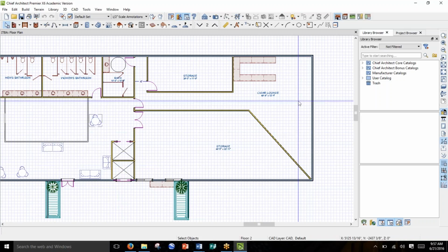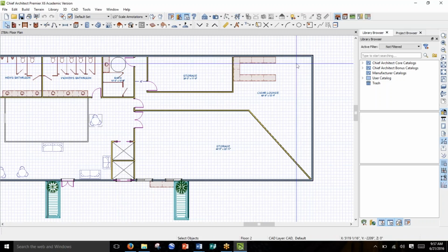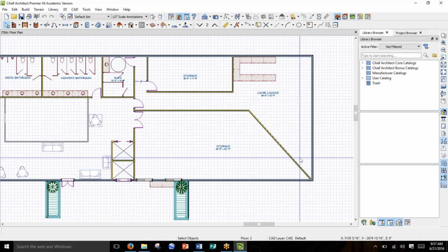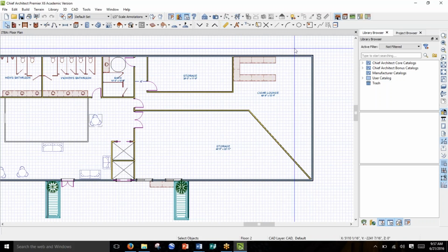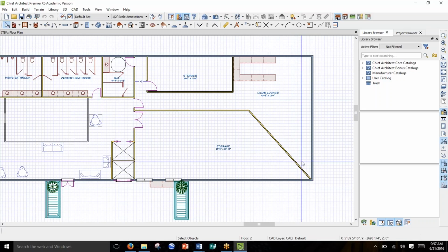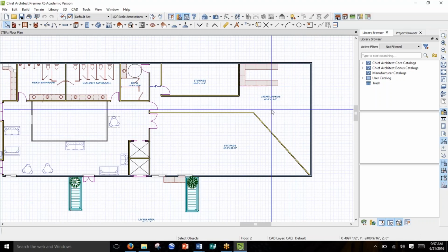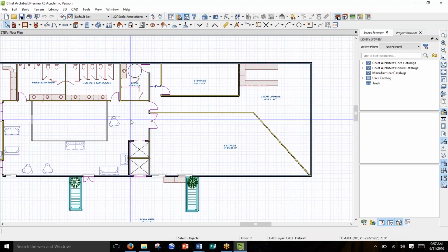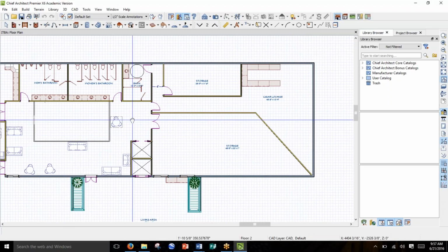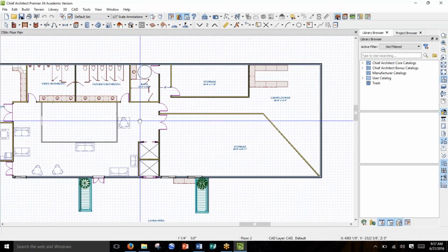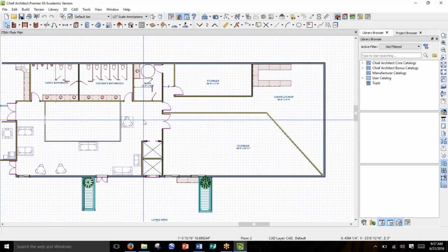If you could show me a diagram of some measurements going from that corner up to the main pathway, from the pathway to the door, and from the door to the elevator, then we could check those, and if you would check them on your end to make sure that it meets the requirement. Now I'm assuming it's going to be sprinklered, so you would want to look at the sprinkler distance, which I think is possibly 300 feet.